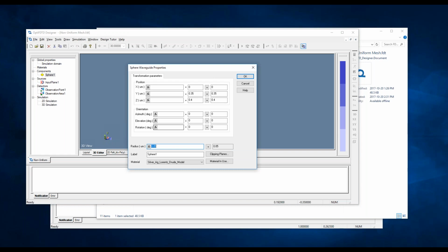But we are actually running a simulation space that's about 10 times larger than this radius. So if we were to try and run a simulation that meshed this radius, which you would want 0.005 at a minimum, so 10 points across the radius of the sphere, you'd be running 100 times larger than you would need over the simulation space, which we want to avoid.